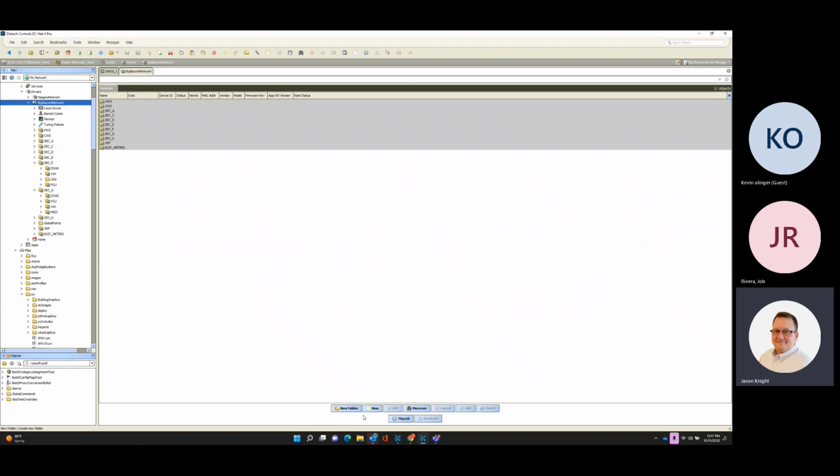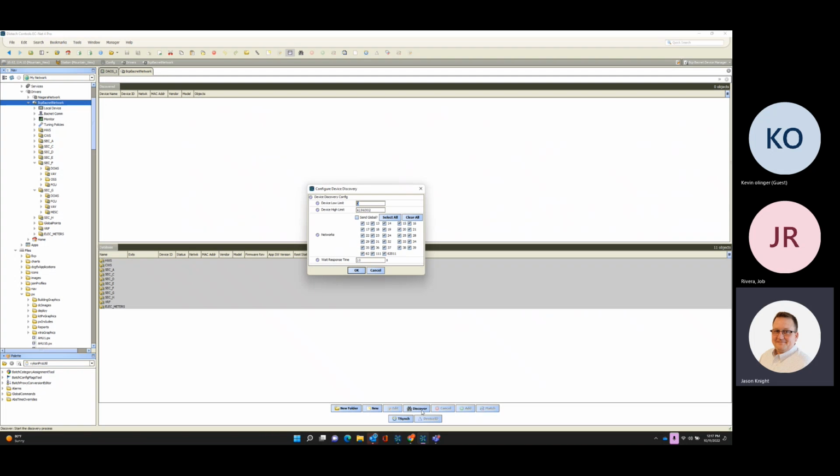So we're going to go into Workbench here, and you're going to look at all your subordinate folders right here on the top. I'm going to click this little Discover button. What it's going to do, in the SoftJS, is look at all your router tables. These are all the BACnet networks that are set up in this campus right now. What do we got? 1, 2, 3, 4, 5. 1, 2, 3, 4, 5. So there's 25, 26, 27, 28. You have 28 individual BACnet networks to get all this stuff to talk and pull together, and talk from MSTP to BACnet IP.